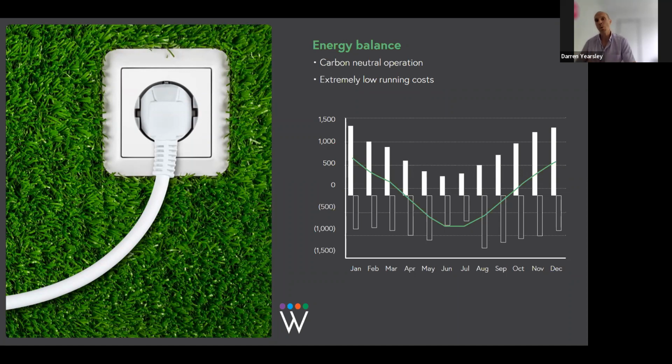So when you get those things matched over the annual period, your energy balance, the capital efficiency of the system is very, very good. That's where we're getting to cost parity with an electric element system at about 50 apartments.